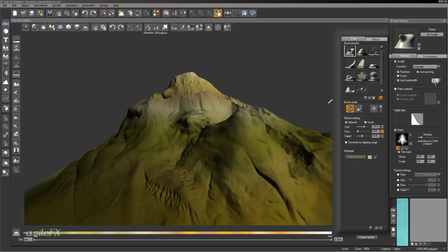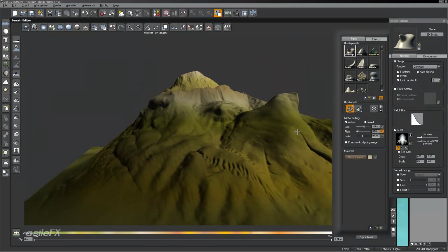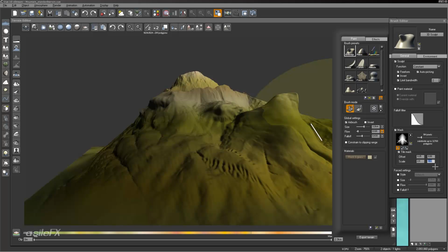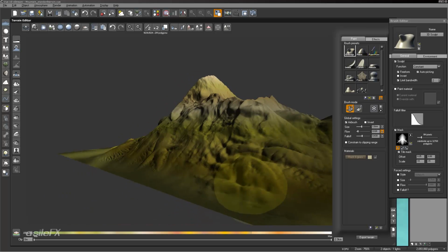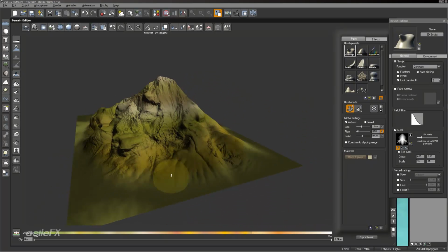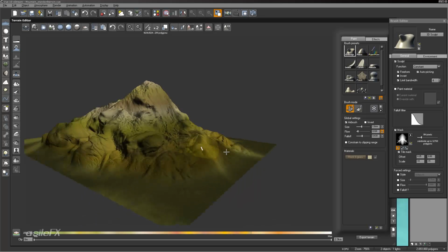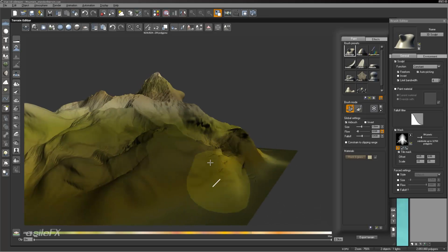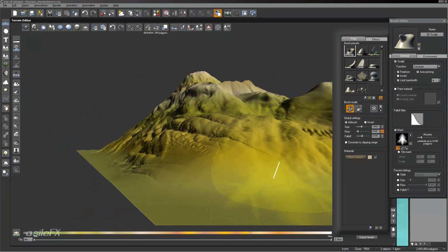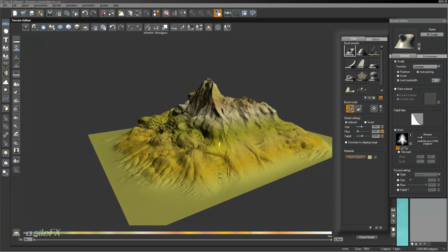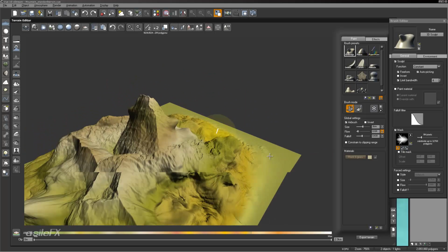And it looks like we're going a little bit beyond the resolution of the image, so we can limit the bandwidth to avoid the pixelation. Maybe we need to just scale it down a little bit. I'll do 1.5. And we can bring our bandwidth up to, say, 4. And get even more detail. And then if we want, we can just turn off that tile mask. And then we can just paint it in with a single brush. Go ahead and rotate it.